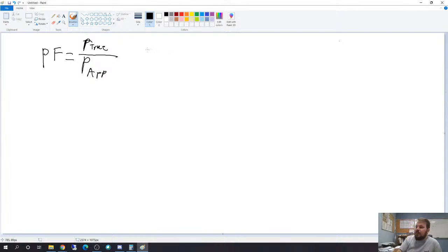We are at 63, so that's going to be 0.63 is equal to 25,000 watts over P true. We don't have P true yet, but we can get it.